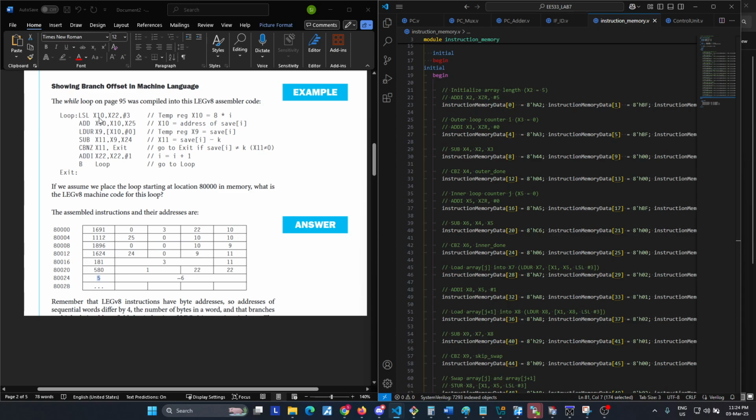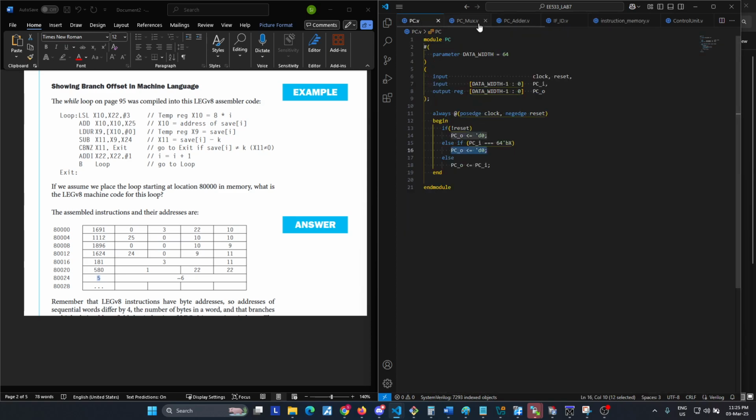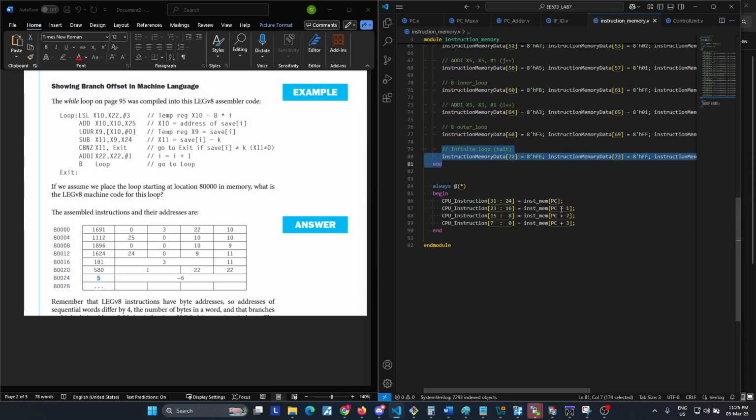Finally, this is an example of how the loop will work. This is an example of how the instructions will be saved in the instruction memory, and since we are making a byte-addressable memory, the instruction memory increments for each and every single byte. For the MSB, we'll have PC. The next byte will have PC+1, the next PC+2, and finally for the last byte, we'll have PC+3.